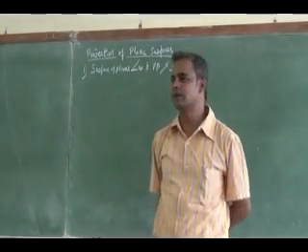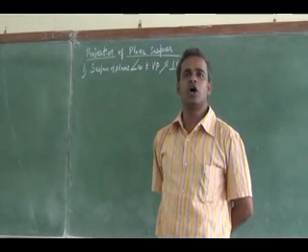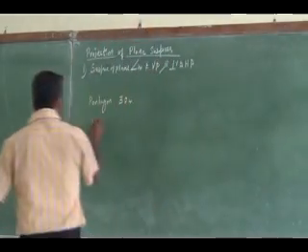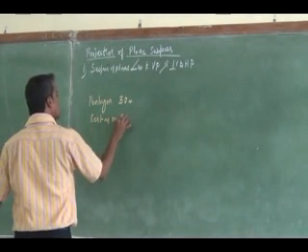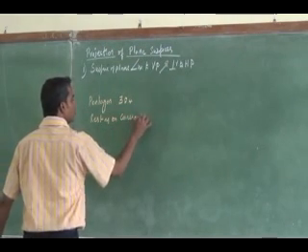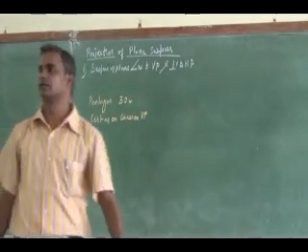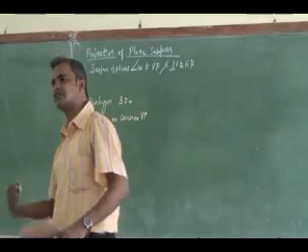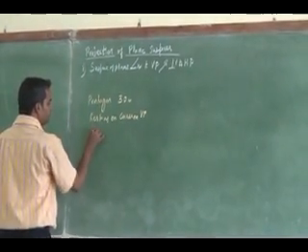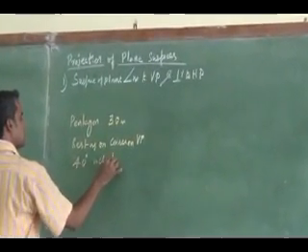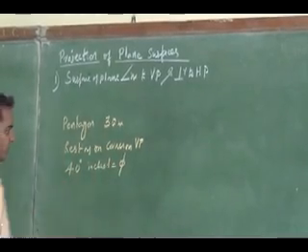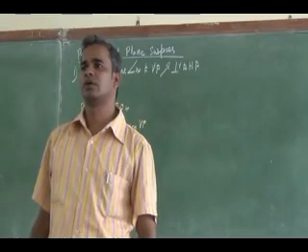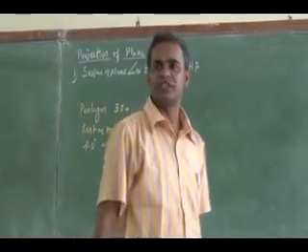A pentagonal plate of side 30 mm is resting on the vertical plane with one of its corners, resting on a corner on VP, such that the surface of the plane is 40 degrees inclined to VP, and perpendicular to HP.